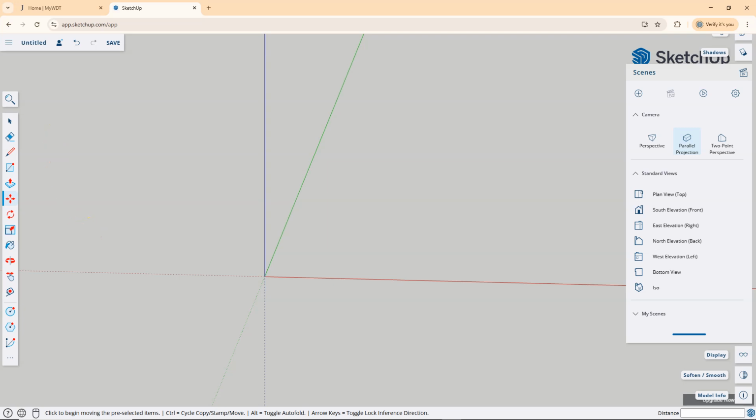So what I'd like for you to do is draw the rectangle that's going to be sort of the footprint of this house. And I want you to make it 30 feet wide and 46 feet long. Okay, so 30 in the X direction, 46 in the other. We'll use the rectangle tool for that. We'll kind of move it out in this direction here. We can be certain that the narrow direction is X in this case. And we'll just type 30 feet, comma, 46 feet. Enter.